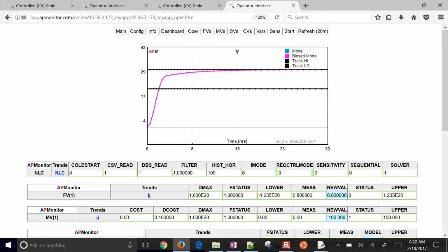Now this is changing it to a pure deadband. Instead of starting here and then coming up at a gradual rate, it just says I want you between this upper and lower limit and get there as fast as you can. So it does it within just a couple points, and it's within this trajectory deadband.